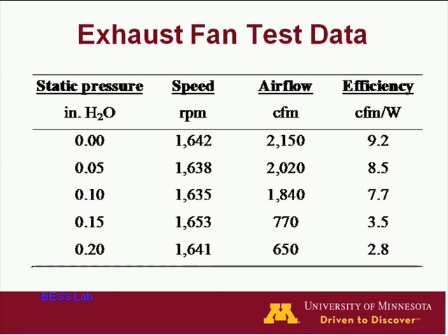We do need to carefully select fans that are rated, and again, Kevin touched on this. This is the test data for a given fan, and it shows different static pressures starting at 0 up to 0.2 inches, and the airflow rate, CFM. As you can see, as the static pressure goes up, the airflow goes down.